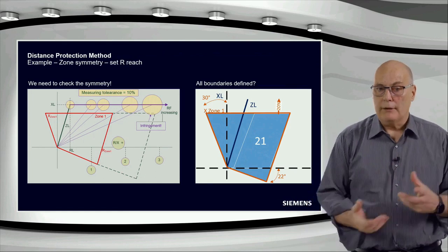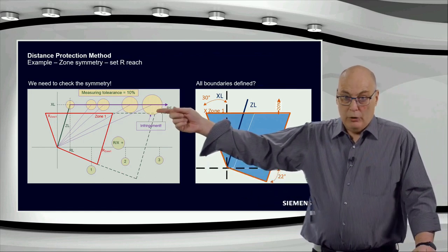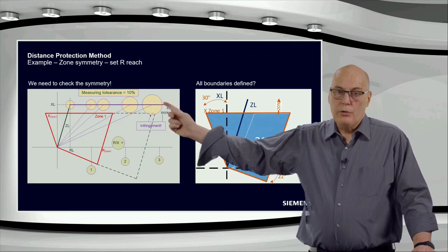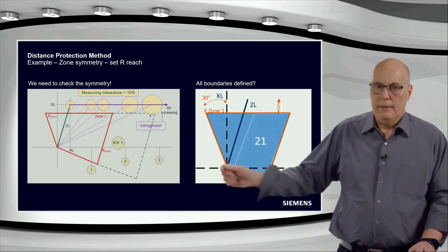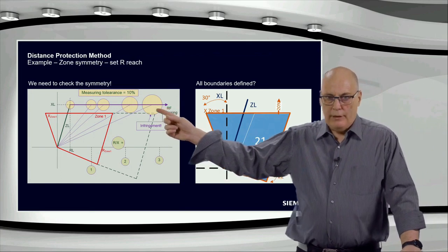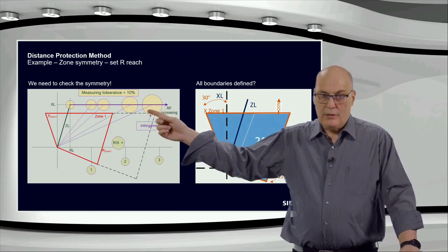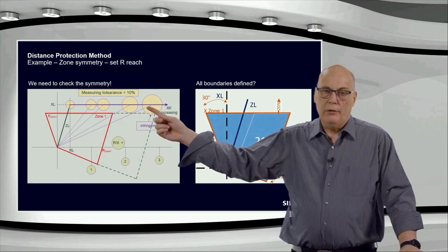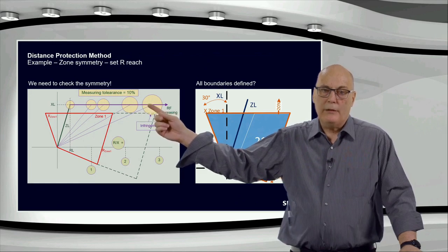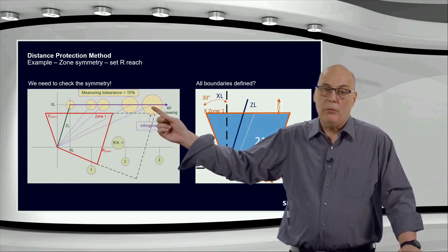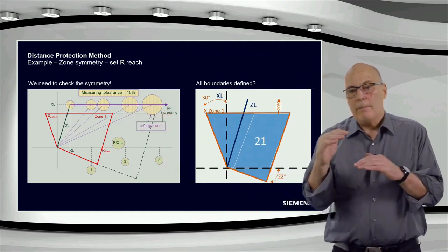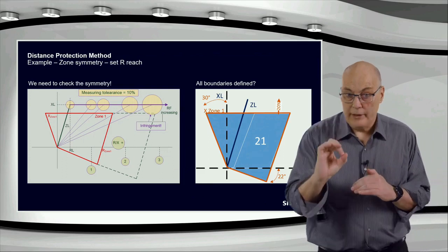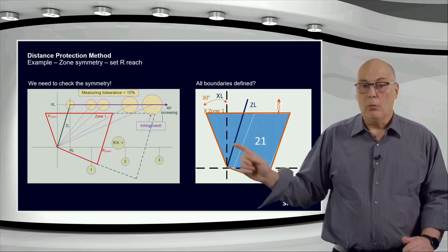So I just made an example and say that the 20% safety margin we apply was used to take into consideration a real tolerance of 10%. If you look at the 10% tolerance on the impedance, you see the circle radius here is showing the tolerance. So if the fault is here, due to 10% tolerance, it can be anywhere inside that yellow circle. And as you get closer to the other side, the impedance gets shorter and therefore the circle radius gets smaller. But what is the problem?